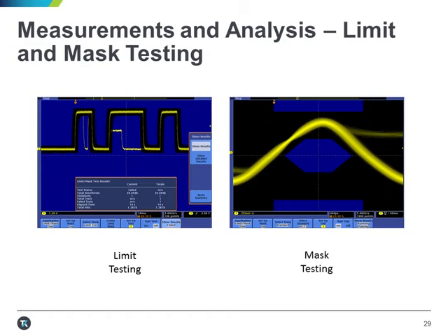If you are interested in this type of testing for general purpose use as opposed to compliance testing, you may also want to look at the visual triggering function that's available on our DPO 5000 or higher series oscilloscopes. This visual triggering allows you to draw shapes on the display and have the scope trigger whenever the signal moves in or out of the shape you've drawn. It's designed much more for general purpose triggering in this regard.